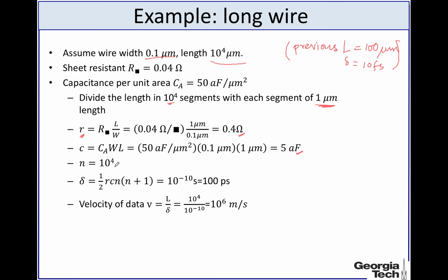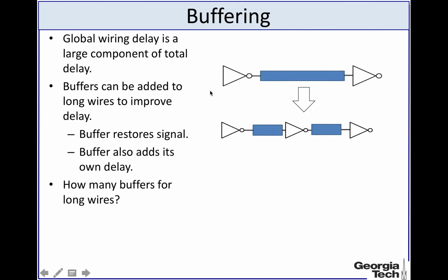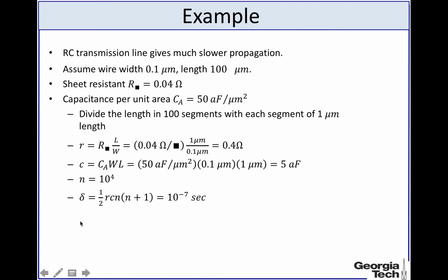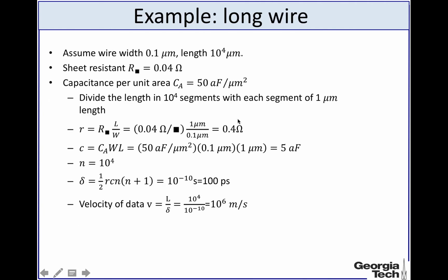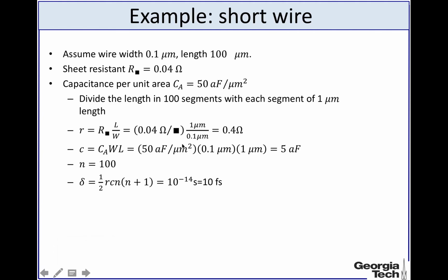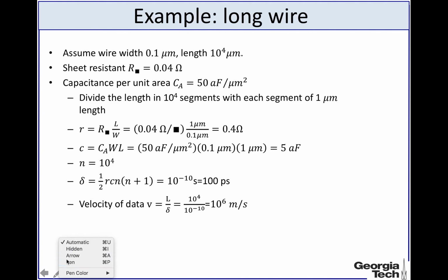The only thing is that since the total length is 10 power 4 microns and each section is 1 micron, we get a total number of sections of 10 power 4, and if we plug in the numbers, the total delay will come out to be 100 picoseconds.